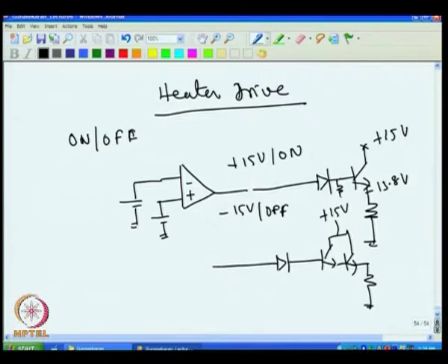To discharge the storage charge, we can have one resistance, maybe around 10K, that serves the purpose here. So, put this, and that becomes alright. The Darlington pair can be used for high power current, because the current in the base cannot be more than 10 milliampere, since most op amps are rated for 10 milliampere output current. In this case, if the HFE of this is say 100, then with 10 milliampere, 1 ampere current can go through this, and the transistor should withstand that much power and heat, because in the on state about 1 volt is there and about 1 watt heat dissipation will be there when 1 ampere current is flowing.